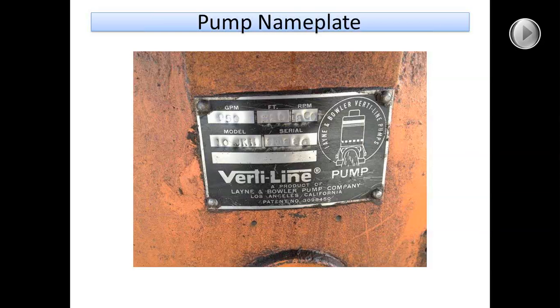And this nameplate also tells us that this pump is designed to pump at 950 gallons per minute at a total dynamic head of 320 feet if it's operating at 1,800 RPM. And so that way I can grab a 10JKH pump curve, and I can see how many stages it would take and what the trim would be to give me these operating conditions.